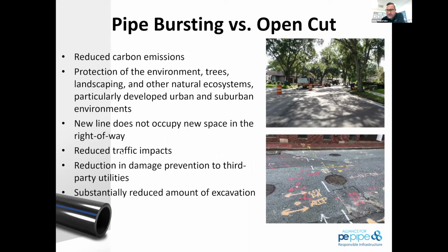Significant reductions in traffic impact, but that's typical with trenchless technology as a whole, being able to get in and replace a pipe in 2 days instead of 6 or 8 days to open cut.